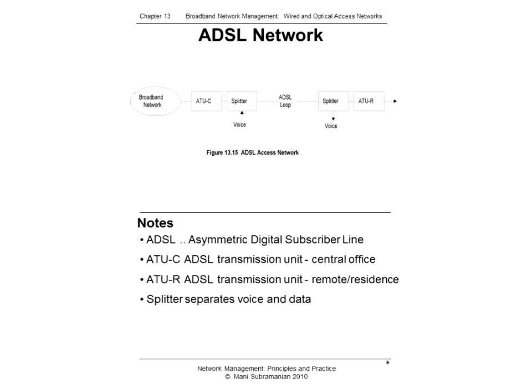Now the data and the video signal from the broadband network is converted to analog signal by ATUC, and it is multiplexed and demultiplexed. Now the splitter over here at the central office combines plain old telephone service, that we call POTS, P-O-T-S. So this is a voice signal and the broadband signal. And the reverse process occurs at the splitter and ATUR at the customer premises.